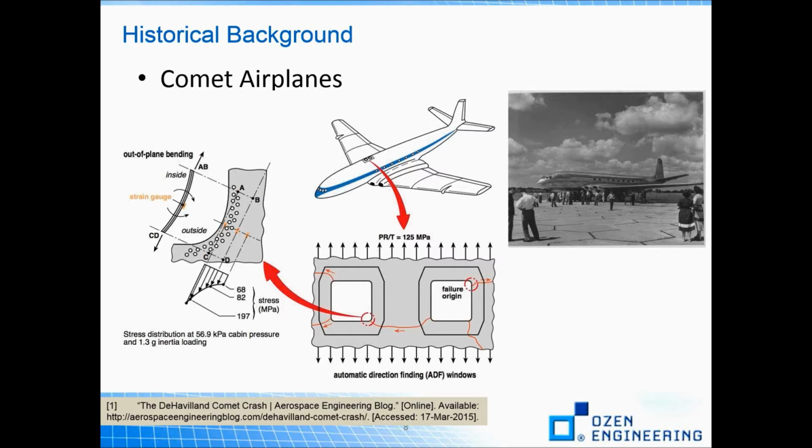after the incidents included pressurization tests of the fuselage in a water tank and fatigue cycling, and the evidence of fatigue cracking was found on the corners of the escape hatch and side windows. There were lessons learned from these accidents.